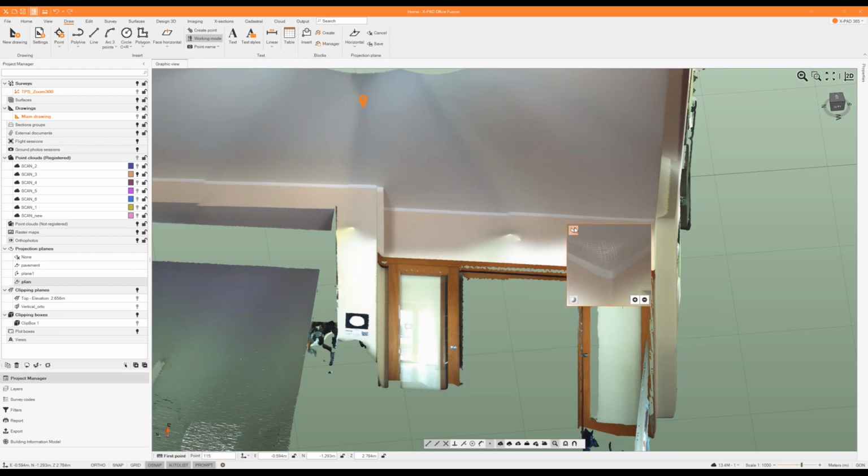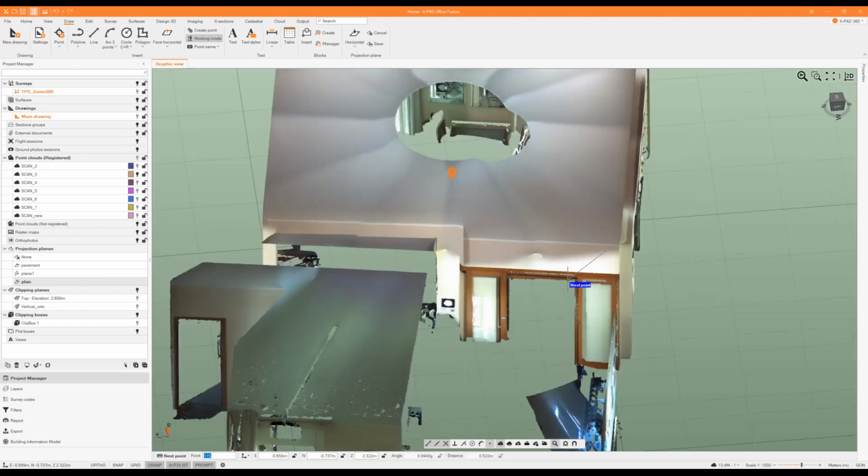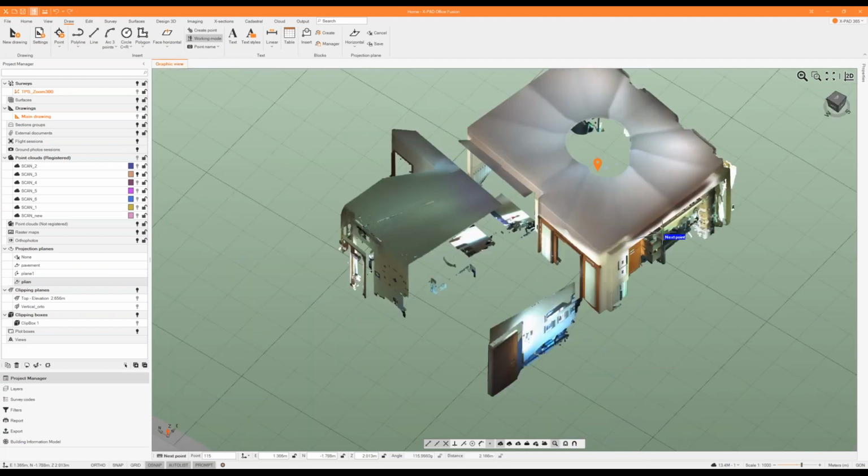And here we have also some other option, automatic plane recognition. This is quite important because if part of the point cloud is missing in the angle, we can use one point of one of the two planes and automatically it will be projected to the center. And then type of selection, sphere selection, or another selection that I will show you later. So in that case, I can simply select the angle.